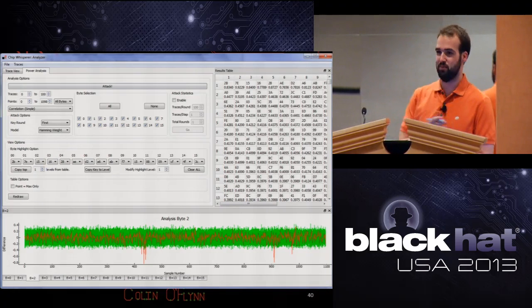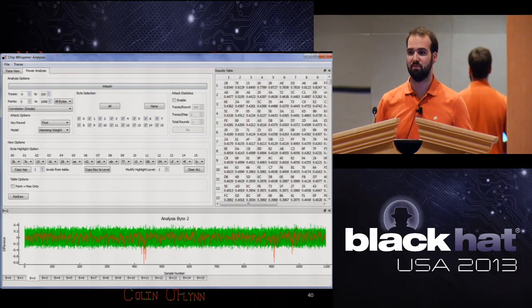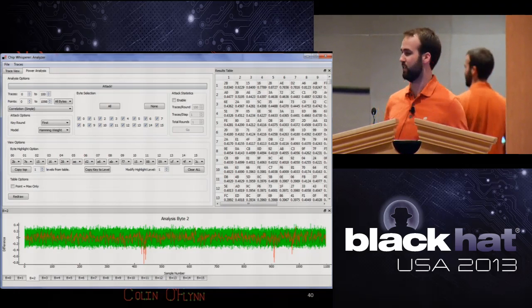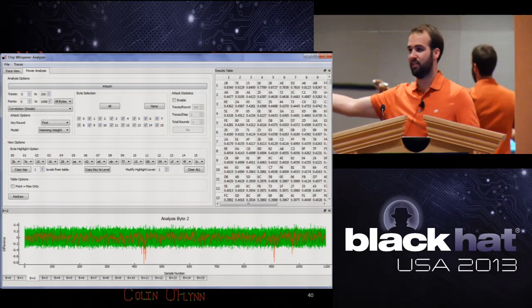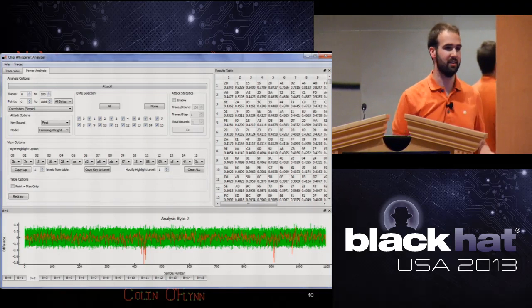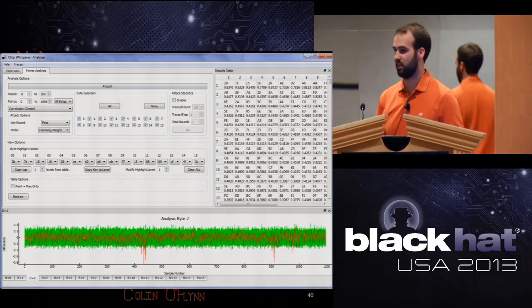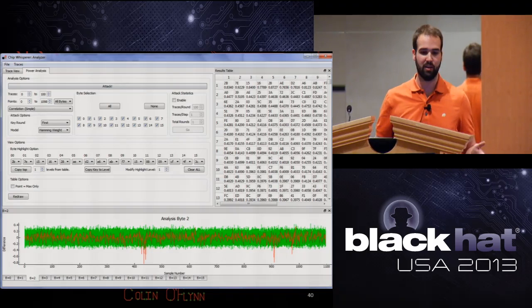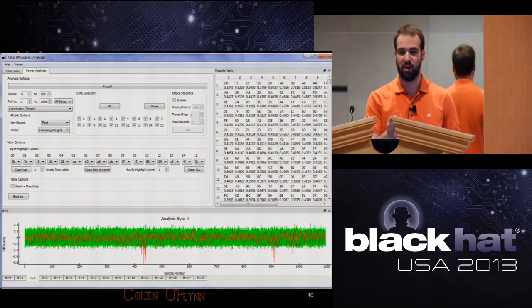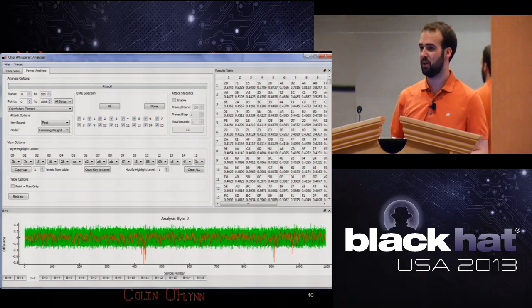So you don't know when it was doing the S-box. You have no idea, right? I'm just triggering this based on, I send it, do encryption. It does a bunch of stuff, receiving data, subroutines, until it gets to the point. So you just have to be able to record around where it's doing the encryption, and you can figure out where it did it.